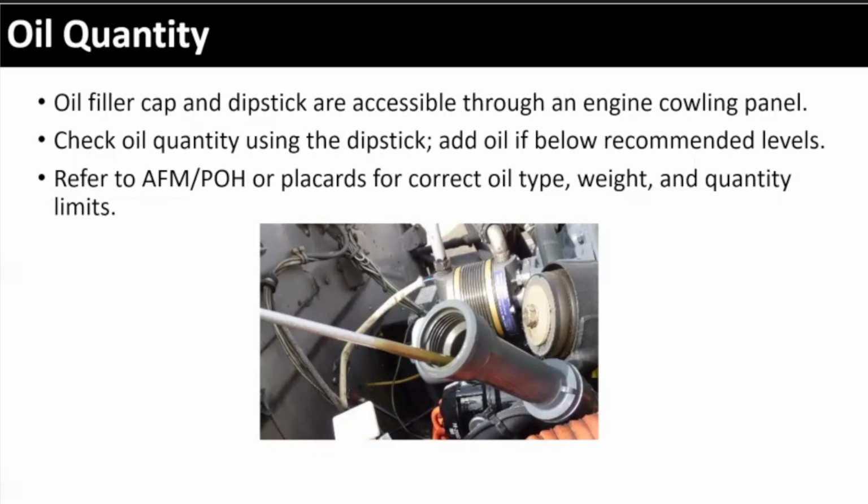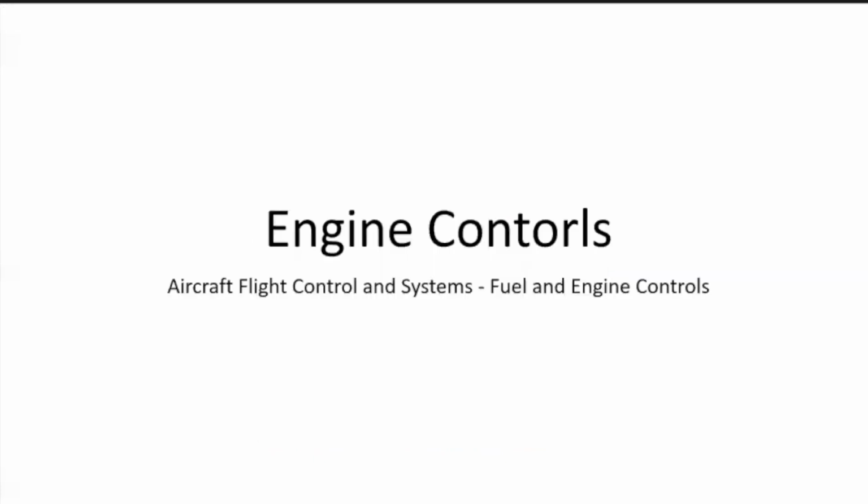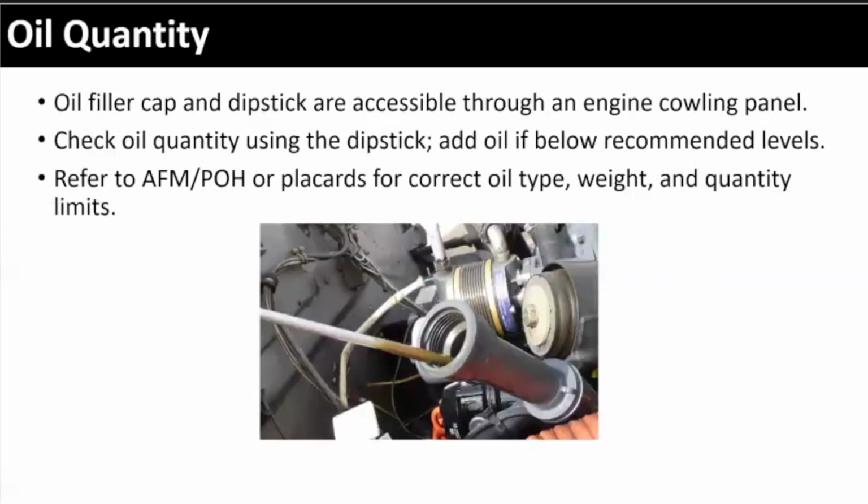Nobody checks the oil in their car, right? Does everybody know how to check the oil in your car? Same thing. Every plane is going to have what looks like a big tube coming out of the engine with an oil dipstick. So on that dipstick, where's the full? I'm looking at that dipstick, I don't see any full line. You can barely see it, it's right there at the top. They're really small indicators, little tick marks with a number. It'll typically be 4, 6, 8. Yep, it's marked.